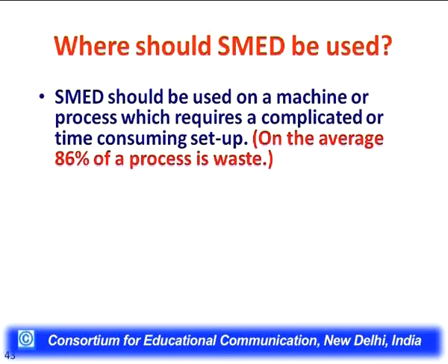Then we should map the process. Each setup process should be mapped. Then areas where modifications are possible should be recorded in the fourth column. And next, we should see how they are going to be modified so their setup time is reduced, operations become easier, and operations become safer also. When this has been recorded, then this should be implemented also.